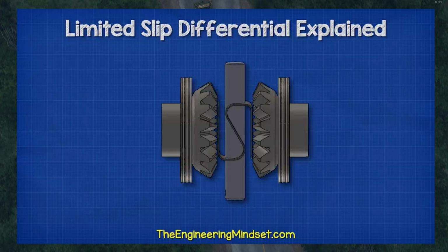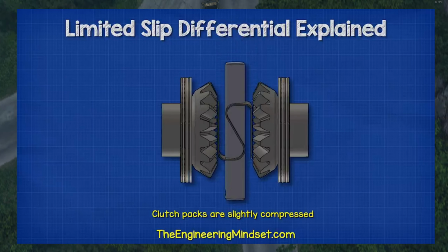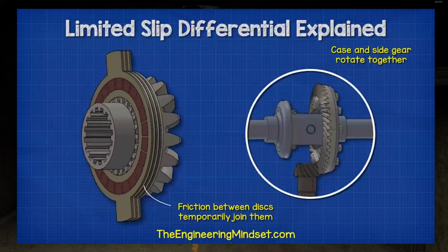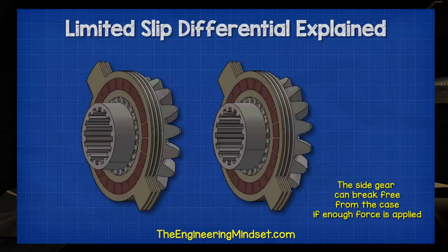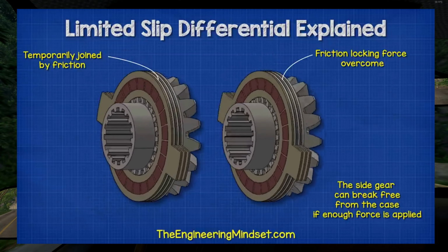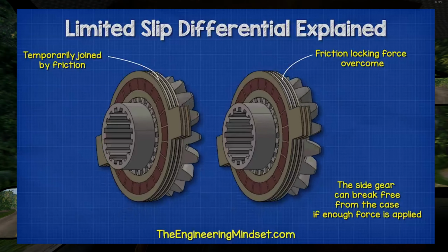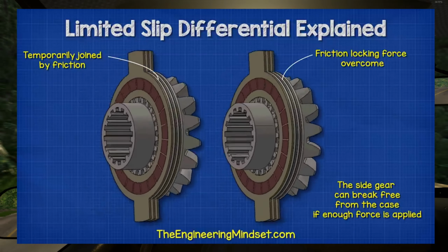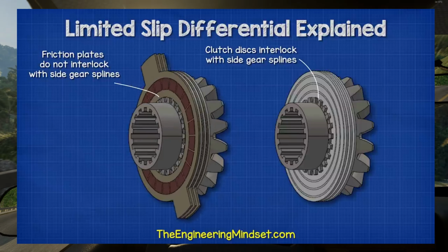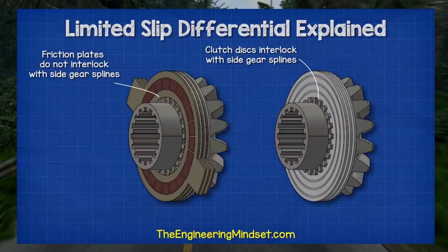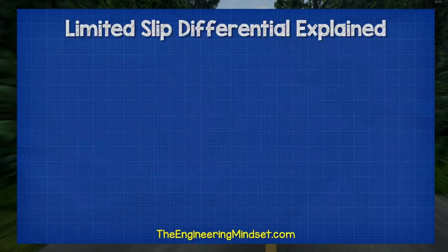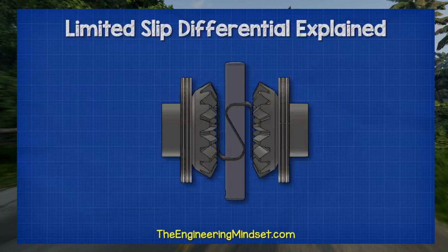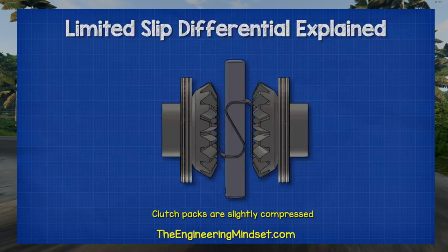Let's consider how these plates are specifically arranged. They are placed 3 plates of each type on one axis, namely behind the sun gear. They are placed in order one after the other, namely first there is a gear with teeth, then a plate with increased friction, then again a gear with teeth, and so on. What is interesting is that despite the fact that they are placed next to each other, they are fixed on different parts of the differential. Gears with teeth are fixed on the axis, and the plates with friction are fixed on the mechanism itself, which rotates due to the crown gear. That is, they receive torque from different parts of the differential, and accordingly, sometimes different torque. The spring between them is fixed in order to compress all these plates together, so that they have a clear contact between the two surfaces.